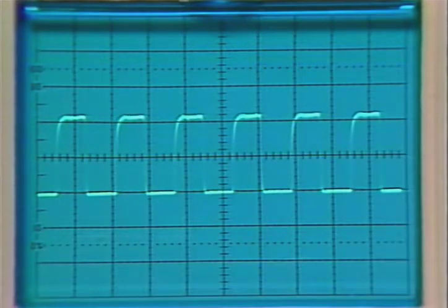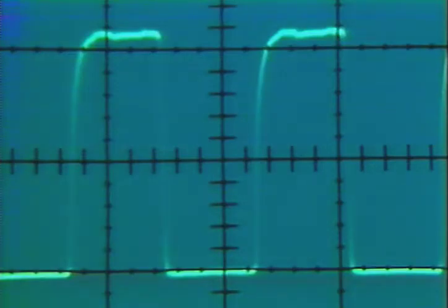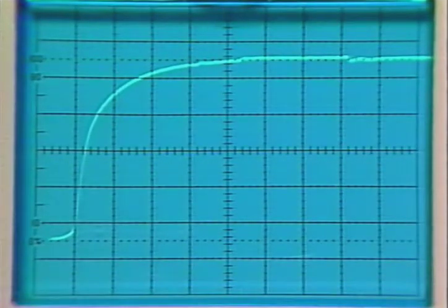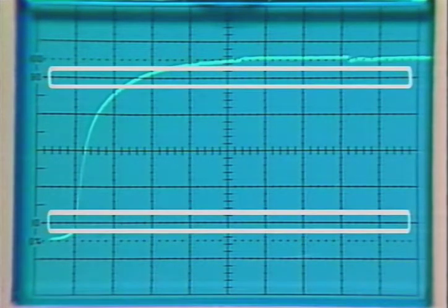Though different-sized CRTs may be used, graticules are usually laid out in an 8x10 division pattern. The labeling on scope controls always refers to these major divisions. The tick marks on the center graticule lines represent minor divisions or subdivisions. These help measure features that are fractions of whole divisions in size. Rise time measurements are very common, and most scope graticules include rise time measurement markings, dashed lines for 0 to 100% points, and labeled graticule lines for 10 to 90%.